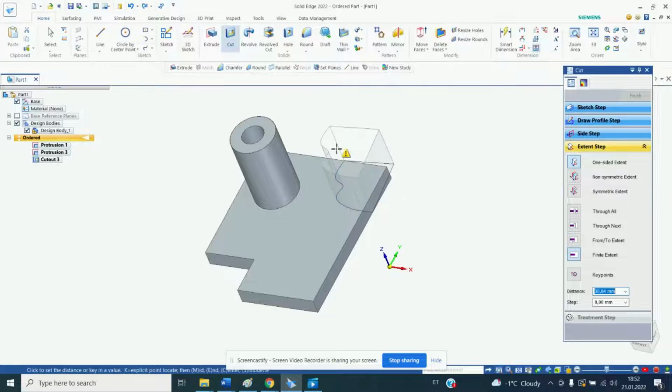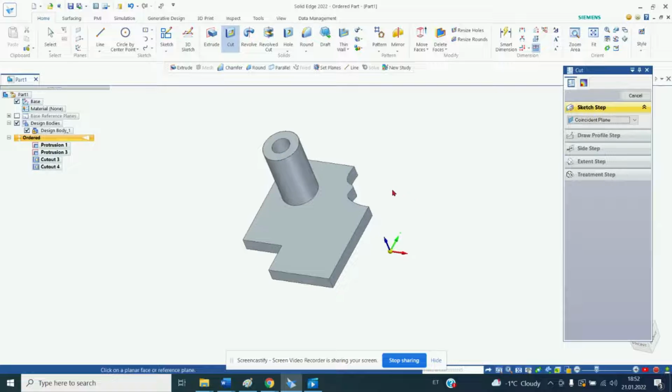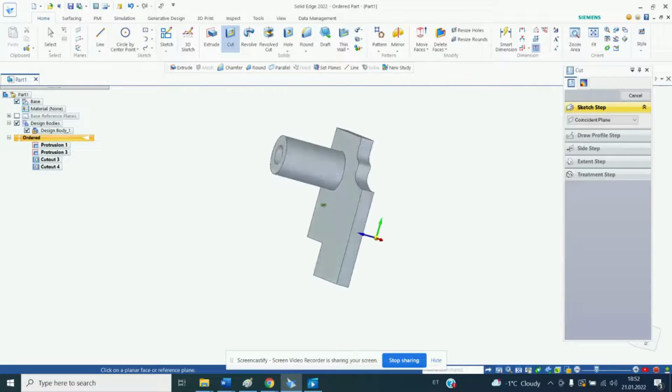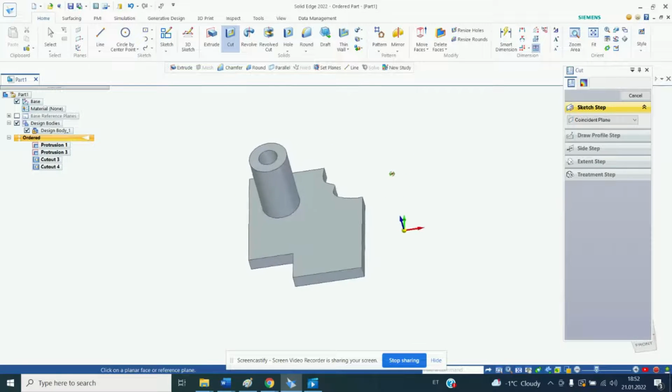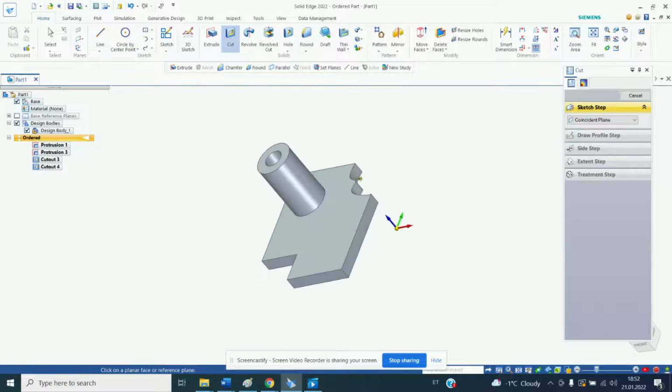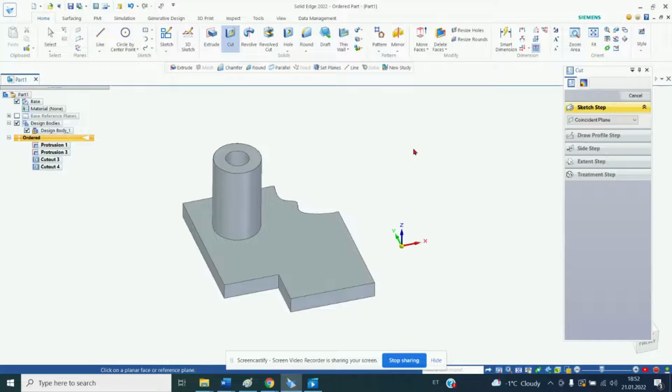Now you have skills to make very basic shapes in Solid Edge. There are a lot of shortcuts to do different things, but all include these steps. For extra, we can make our model more beautiful. Select Round on the ribbon bar and enter radius 3 mm.